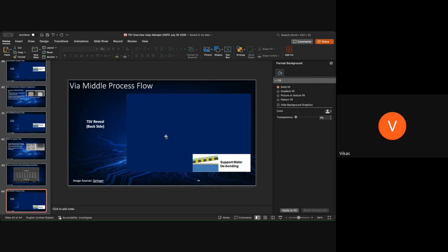I have one question regarding the scaling. As Dr. Uday mentioned, we're going to ruthenium. Do you see ruthenium playing a critical role here? And what are your views regarding the scaling? I know 1:10 is a typical aspect ratio, but in terms of wafer thinning and TSV scaling, from 5 micron to 1 micron, or do you think it's going to go even lower than that?